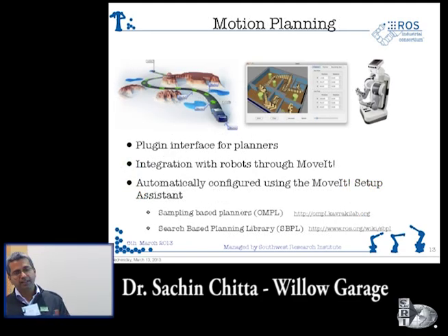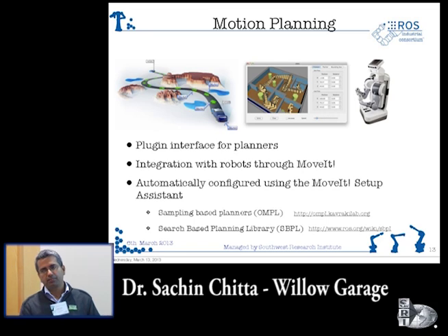So the real meat of what you get with MoveIt is an integration with the motion planners. And the way we've designed the architecture, we've tried to make it as flexible as possible. So if you have your own motion planners, if you have your own implementations, it's very easy to integrate them because there is a simple plug-in interface that you can just use. But we provide two sets of motion planners. So one is called OMPL. So this is joint work between Willow Garage and Rice University.